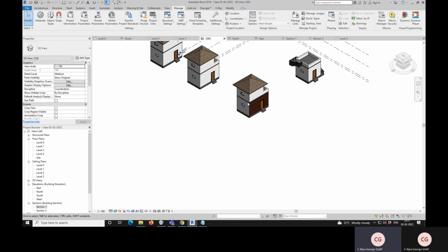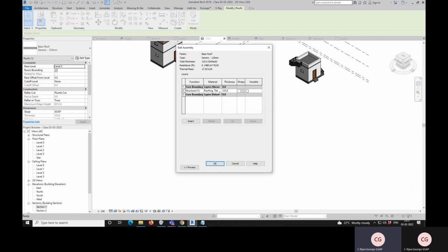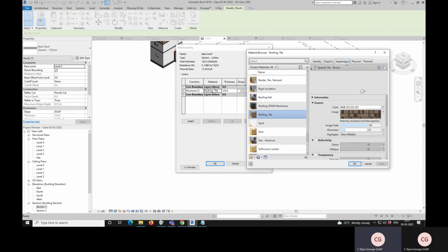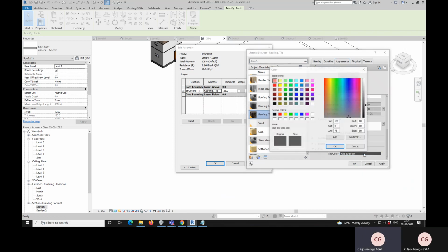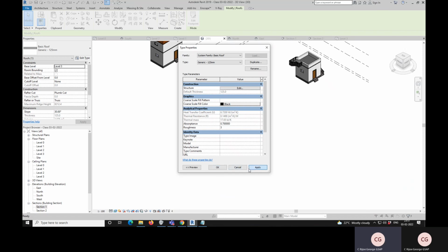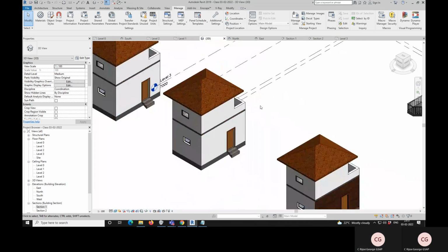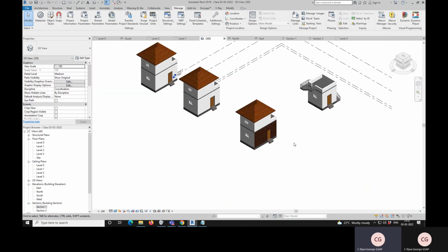This way you can change the color of anything, even the roof. I want some believable color over there. Edit structure. This is already a roofing tile. But go to appearance. See, the tint option is there. Select that and give some nice orangish color. Looks like a Spanish tile. You have a nice roof color. This way also you can adjust the tint of the material.